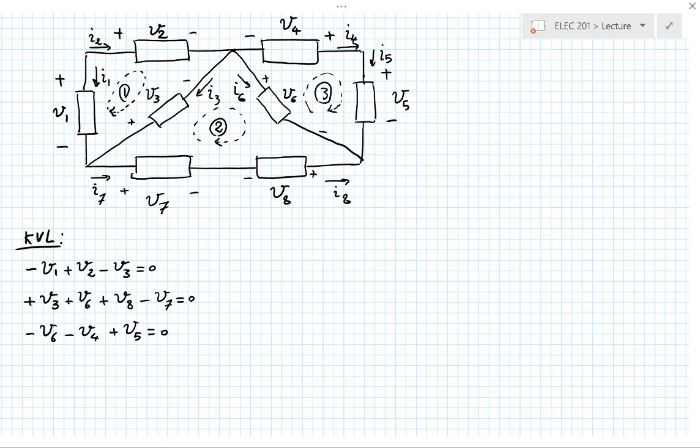Now, let's work backwards one step. Each element, a resistor, capacitor, or something, will have a relationship, a formula that connects its voltage and current, right? That's the identity of the element. So each element will at least give you one equation, right? So out of those 16 equations, 8 will come from the elements. So you need 8 for the number of KVLs and KCLs here, right? So, KVL and KCL? No. No. So we'll see here.